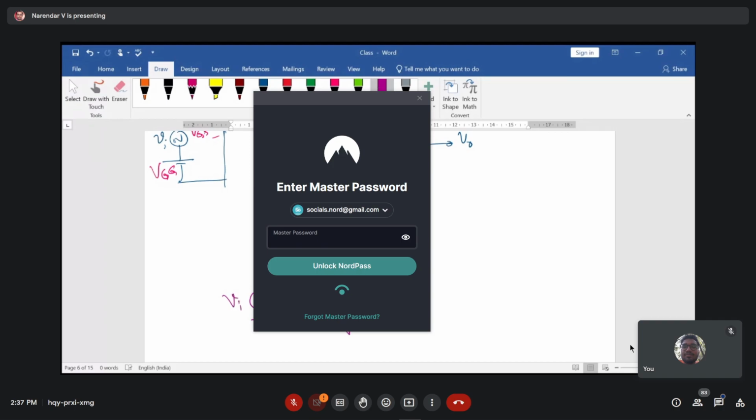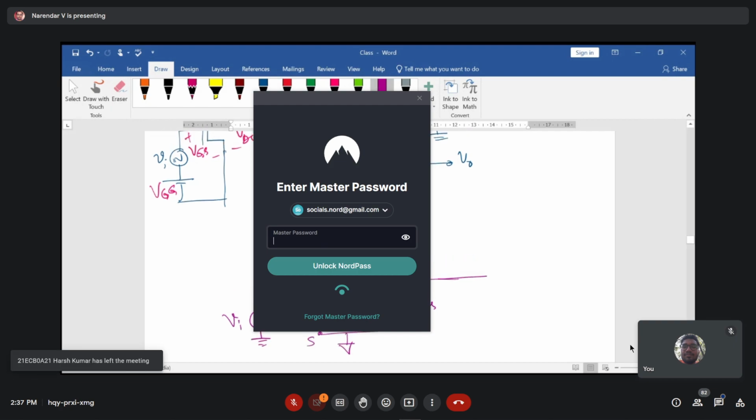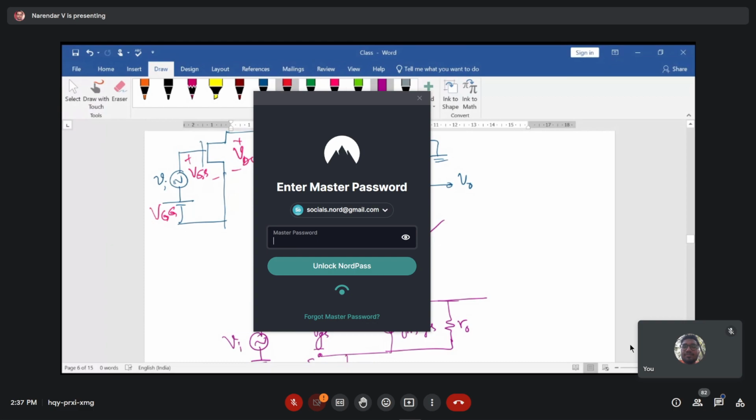Here what you can see is gm times VGS, and this is your drain terminal. Okay, so now you see the three terminals of your transistor: source is connected, gate is connected, and drain side along with this. If there is a channel length modulation factor, let's account for that also, which is R0. This is for your transistor, and then an extra component, RD, is connected there.